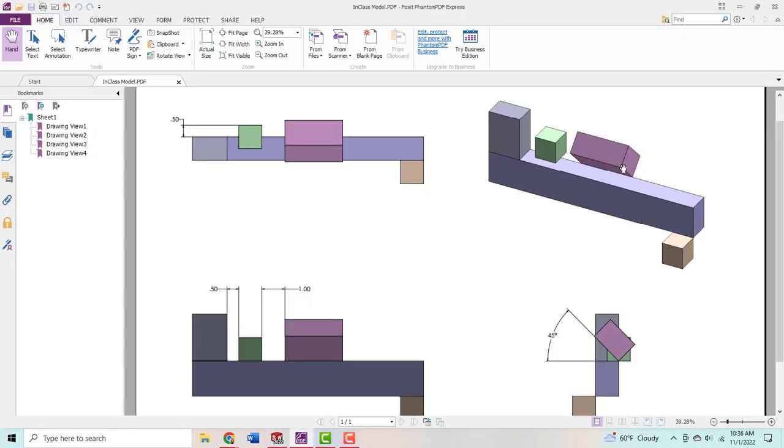So now looking at the pink block, we can see that it's going to have a distance mate between those two side faces of 1 inch from that green block. Its back edge is actually mated to the edge here, and also notice that we're going to be working with the longer side, so it is tipped up, so that shorter side will be hanging off.